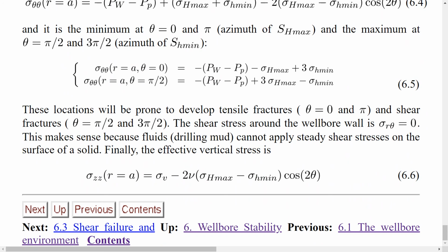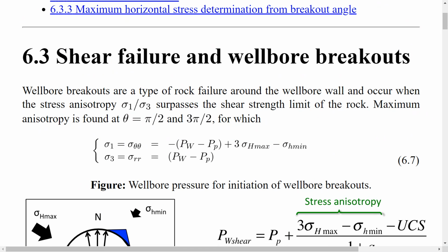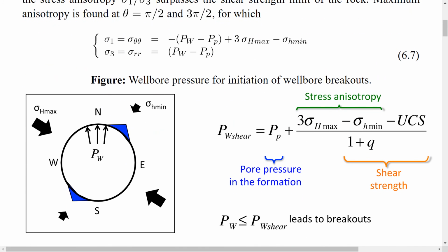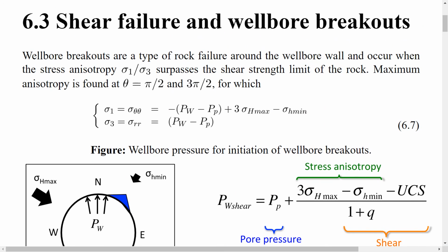So what we're going to do next class is use this equation, and combine what Kirsch tells us with what we already know of rock failure, with tensile strength and with shear failure, to see what the limits of the stress and pressure inside the wellbore are that allow us to predict when the wellbore is going to fail or not.